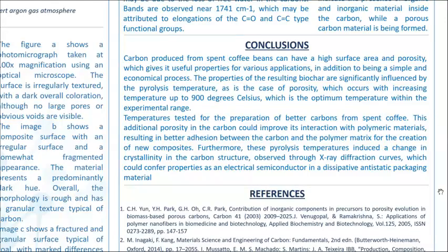This additional porosity in the carbon could improve its interaction with polymeric materials, resulting in better adhesion between the carbon and the polymer matrix for the creation of new composites. Furthermore, these pyrolysis temperatures induced a change in crystallinity in the carbon structure, observed through X-ray diffraction curves, which could confer properties as an electrical semiconductor in a dissipative